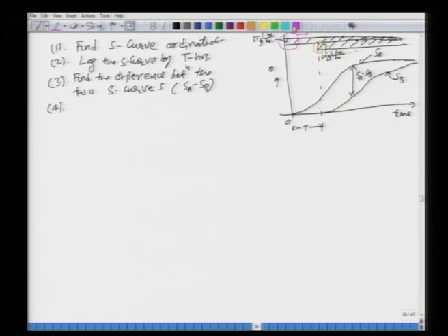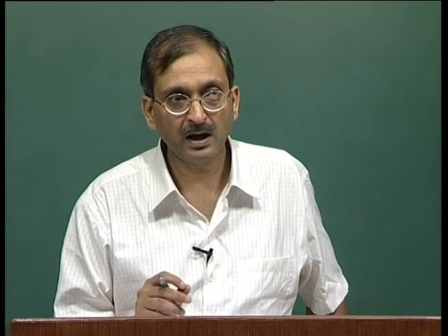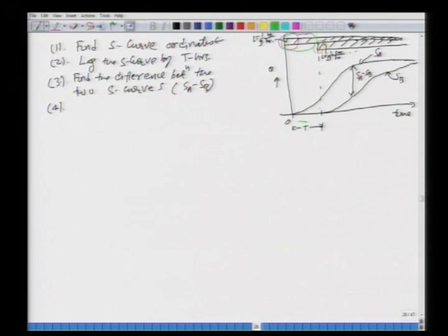That is resulting from which input? It is basically this input. Do you see that? It is resulting from an input of intensity 1 by d centimeters per hour occurring for how much duration? T hour. Do you see that?